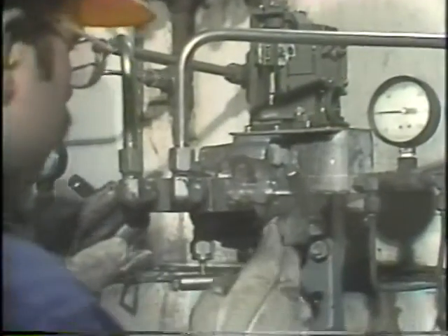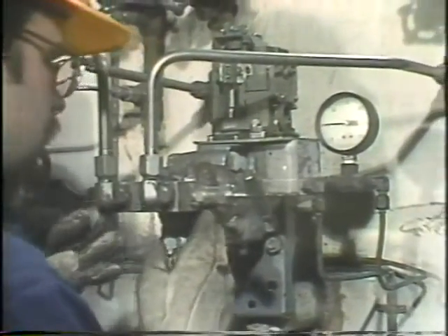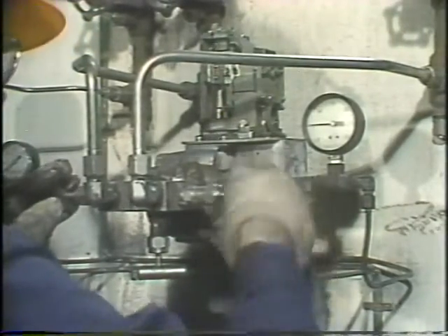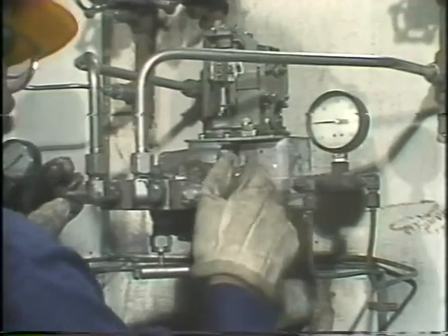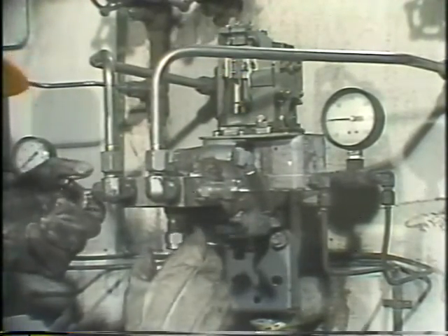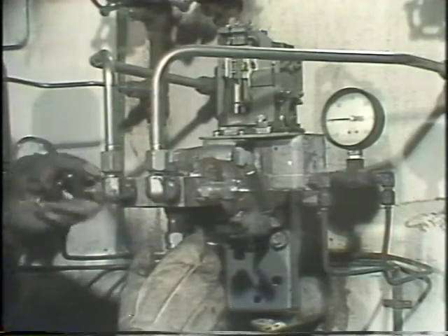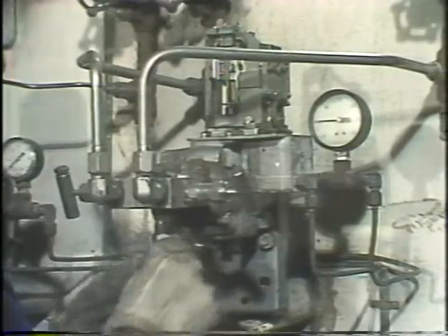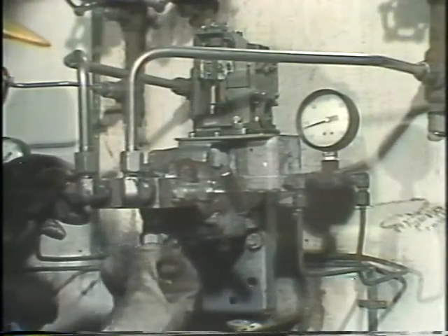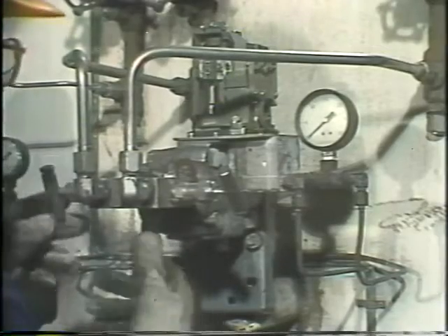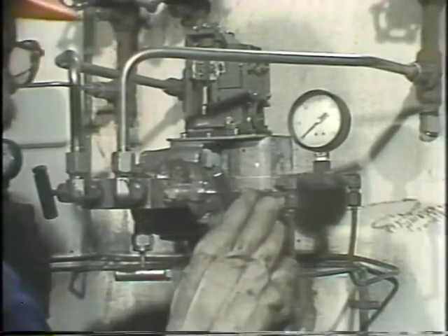Well, there is one check I can make while I'm here in the field. By valving out the transmitter, I can check its output with no input. Close the high side valve first. Now I'll close the low side valve. That's this one over here. Get this valve closed off. Now I open the equalizer. That'll equalize the pressure across the DP cell. With no differential pressure, the output should be 3 psi.